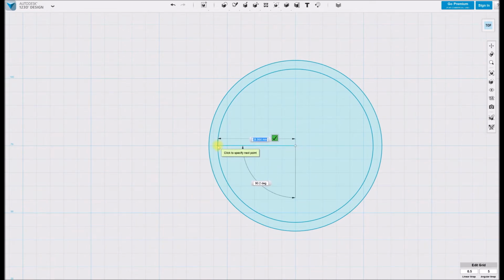So the first dimension that we want to do to line it right up with the minor diameter circle is you want to go to 28.5. That's half of your minor diameter, which is 57. So enter, and then we want it to be exactly 90 degrees, enter. So then to unlock those, you hit escape, tab, escape. So then they're both freely moving now.